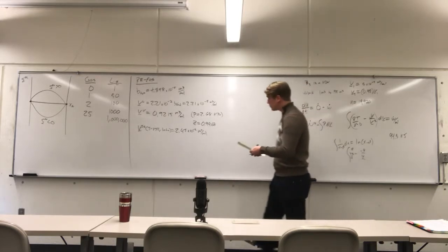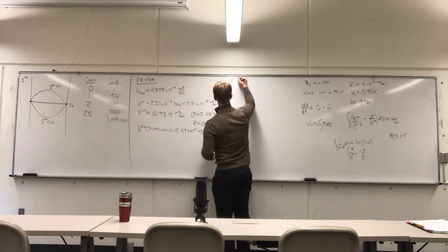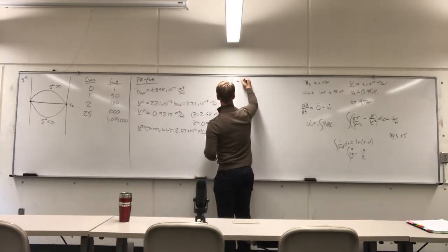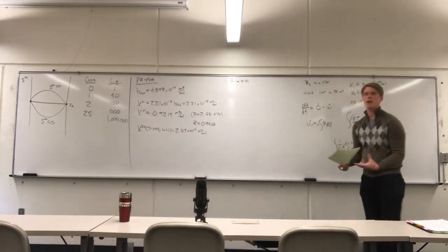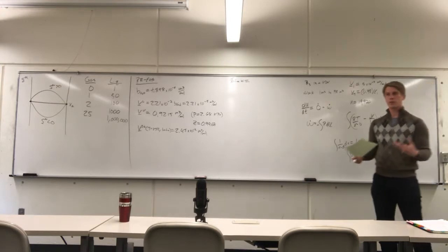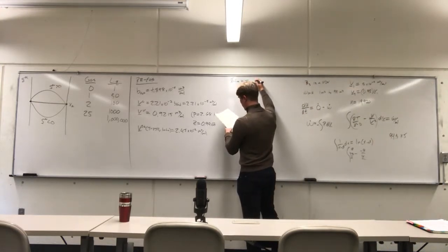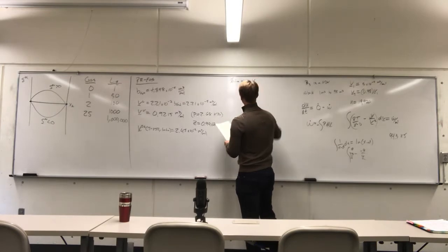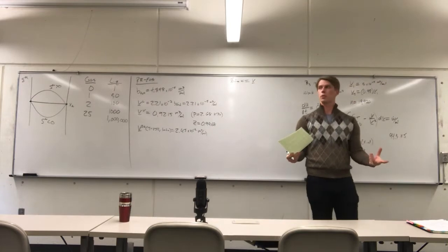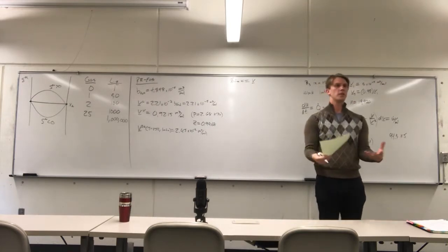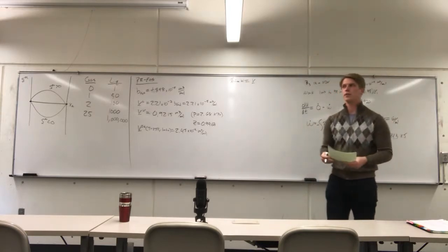So what I calculated was the percent of free volume. That's the percentage of volume that the molecules have to move around freely. So what I did is I took the specific volume of the system, right? This is how many cubic meters per mole that material is occupying. From there I can basically draw a box, and that's the volume that I'm calculating.